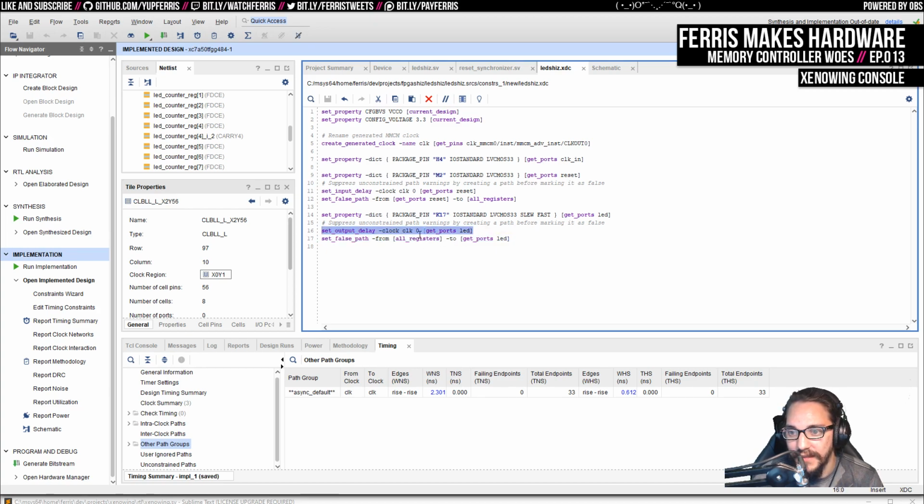So typically you'll specify the min and max output delay that you can tolerate for a specific output pin. And then the nice thing is the tooling will just figure all this out, because the math to figure this out for one path is really easy. It's just that setup and hold time is a constraint on both sides, and it's pretty easy to figure out given all the knowledge that the tools have. And then of course solving that for many of these paths can be really difficult, and if your design has really long paths, it might be impossible.